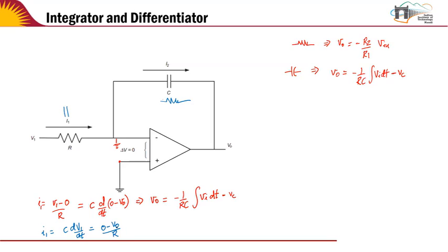I mean, you have to visualize, I have swapped the capacitor and the resistor, and that implies the output V0 is minus RC dVi by dt. Let me call this Vi or V1, just keep it consistent. So in this case, it becomes a differentiator because the output is proportional to dVi by dt. Now the same thing by the principle of duality, instead of this, we could have also proceeded the original way. Let's say I had the same op-amp circuit, the minus plus.